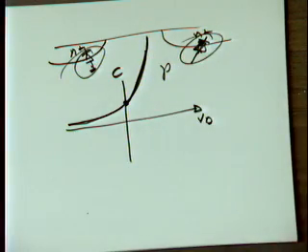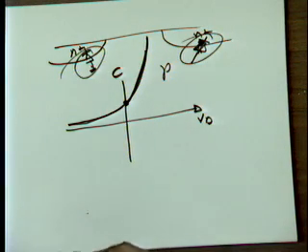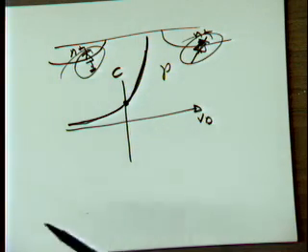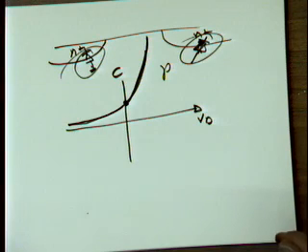Very nonlinear. So as we said, that's a pain in the butt. You have a capacitance that varies quite substantially with the data value, which is very hard for me to do analysis for my propagation delay. So what I'd like to do is replace it by a capacitance that gives you the same charge displacement as the nonlinear capacitance does over the interval of my propagation delay analysis, like before.